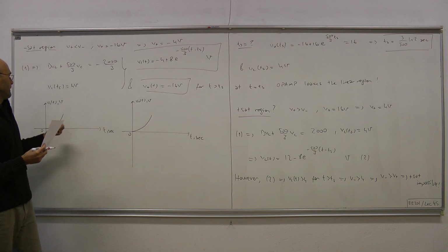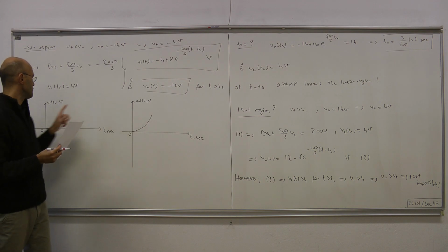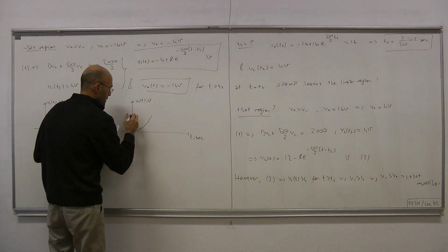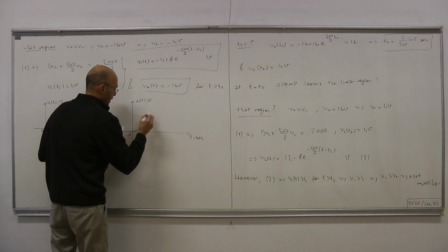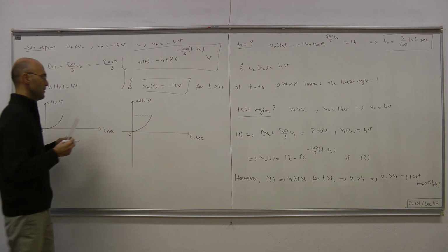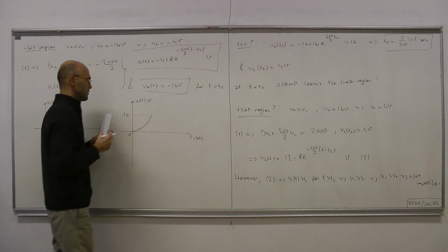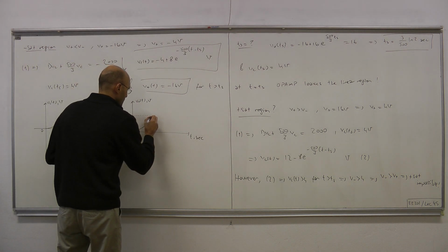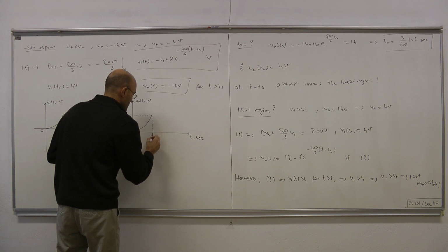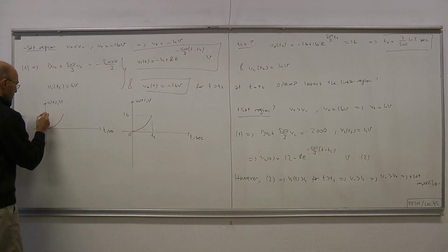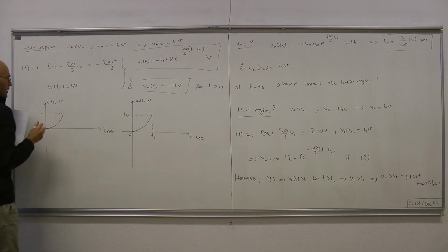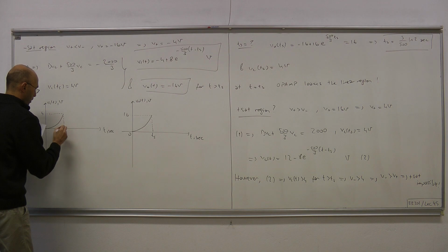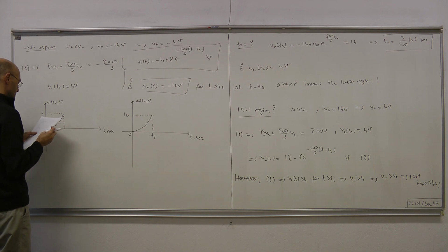Okay, the out is 4 times V C during that time, but eventually the out had to hit the border, which in this case is positive saturation. Okay, it reaches 16, and then the time that corresponds to that is Ts. At that point, the capacitor voltage reaches 4 volts, at Ts.